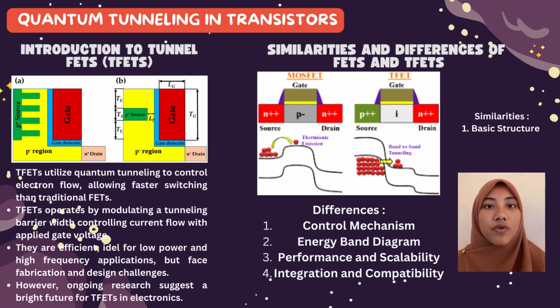The third is performance and scalability. TFETs are made to reduce leakage currents, enable voltage scaling, and counteract short channel effects. Nevertheless, because of the cross-sectional area that might be tunneled and the likelihood of tunneling, they frequently experience lower on currents than MOSFETs. This distinction affects both their overall effectiveness and applicability.